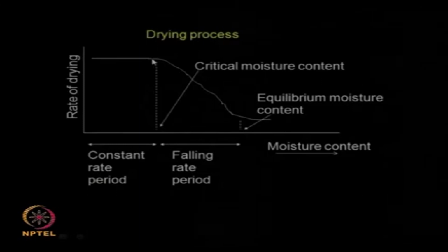Here the only limiting factor is how much heat you are able to supply so that the material gets dried, that means the liquid gets vaporized. So the rate of evaporation is matching with the heat of vaporization, which is also equal to the driving force, which is the vapor pressure of water to the partial pressure of water at that temperature condition.